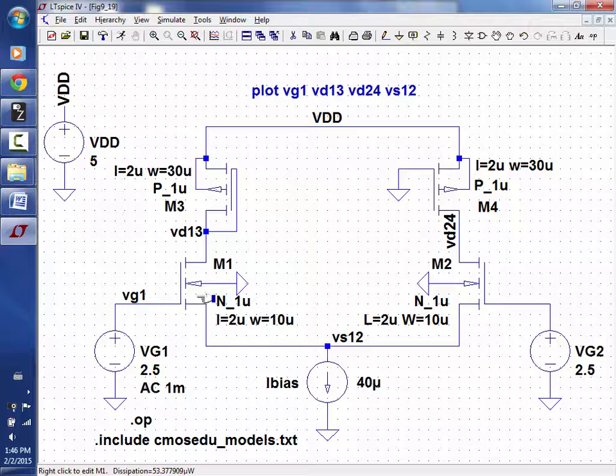First thing I talked about today, what was it? Answering Kobe's question. Output resistance, right? What happens as VDS is increased to the current flowing in the MOSFET? Forget impedance, just real simple. In terms of current, if I increase VDS, what happens to the current? Goes up. Well, here, this voltage is almost 5 volts. This one's 3.85. So this transistor has a smaller VDS than this one. So I expect this one to have slightly more current flowing in it than this one, and it does.